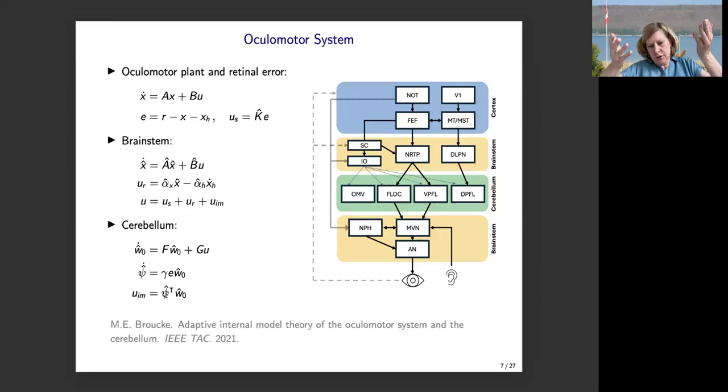Now, as the psi hat starts building up and starts adapting, what it's doing is it's taking the poles of this stable F, which are in the open left half plane because it's a stable filter, and it starts dragging those poles over onto the j omega axis in order to generate persistent signals. Because what the cerebellum is having to do is deal with persistent excitation coming in, persistent signals that need to be canceled. And this is, of course, a very dangerous operation. So very, very dangerous to start to insert this marginally stable internal model of these persistent signals, sinusoids, sums of sinusoids, steps, ramps, stuff like that. So that is what is going on with this parameter adaptation. It is trying to build a model that reproduces the frequency content of those disturbance signals.